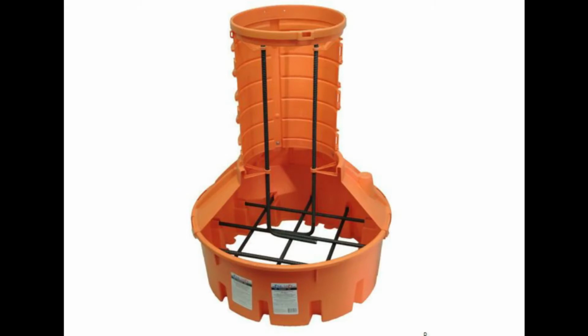When a round pier is to be built, sections of metal or fiber tubes are used. These sections are assembled into what looks like a large piece of pipe. They are set in place on the footing and are plumbed so they stand straight. Then braces are used to hold them in position.